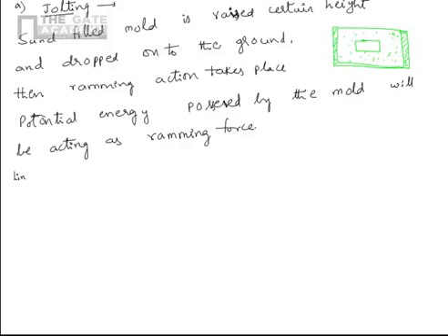So, limitations: the molding sand at the top will be like loose sand, so the ramming action will be non-uniform throughout the sand mold.